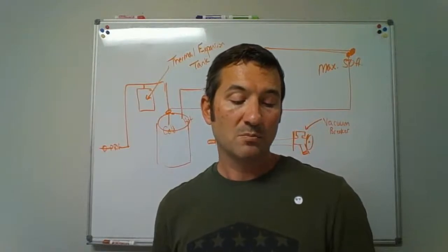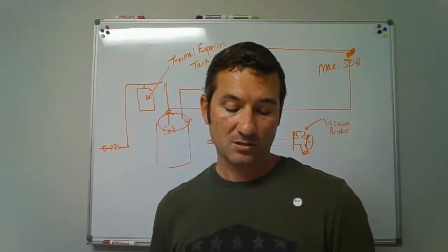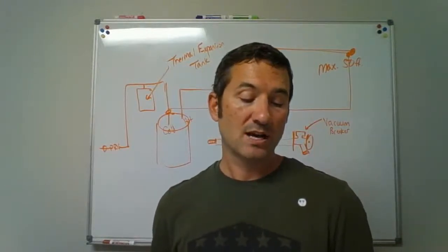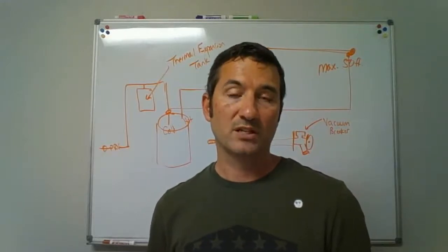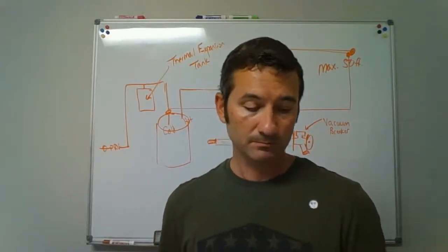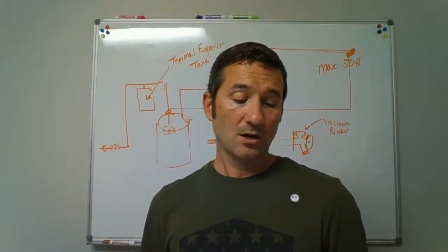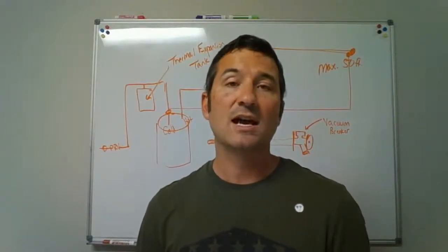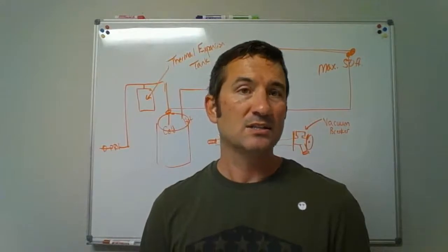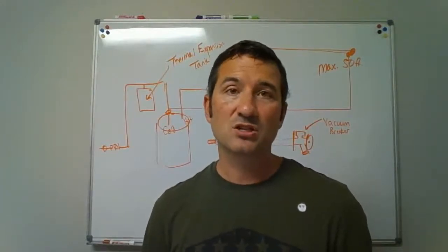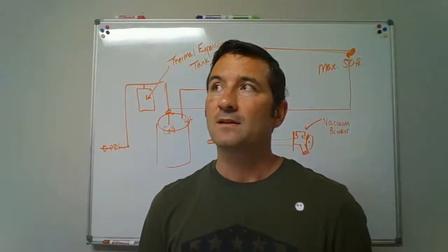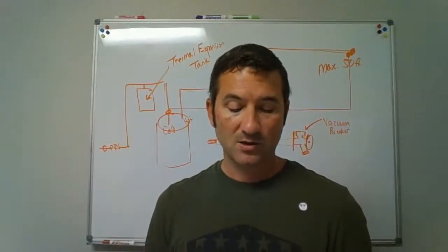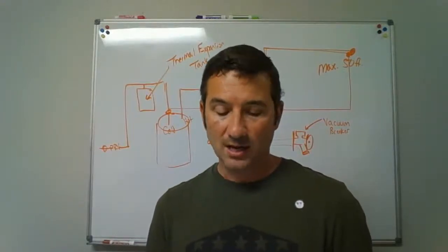Question 2. The minimum size of the water service, the pipe, is 3/4 of an inch. Is that true or false? Number 3, the water service can be in the same ditch as the sewer line. Now, is it possible? I'm not asking you if it stands firm every time, but is it possible to have the water service in the same ditch as a sewer line?